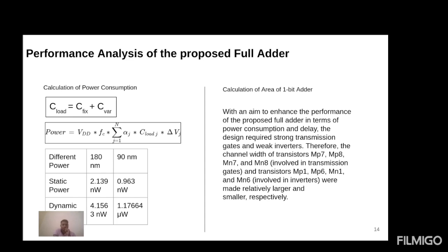In terms of dynamic power, this circuit consumes 4.1563 microwatt in the 180 nanometer design, and 1.17664 microwatt in the 90 nanometer technology.